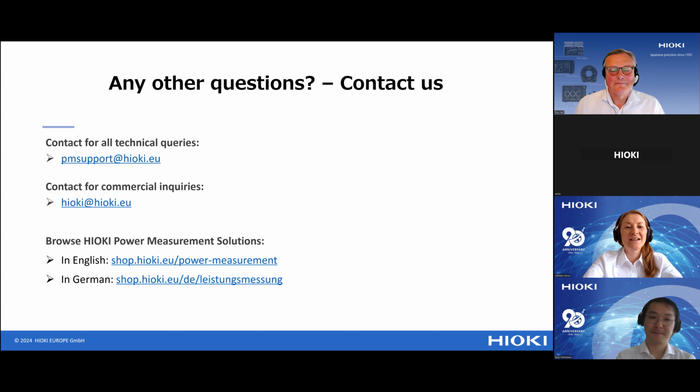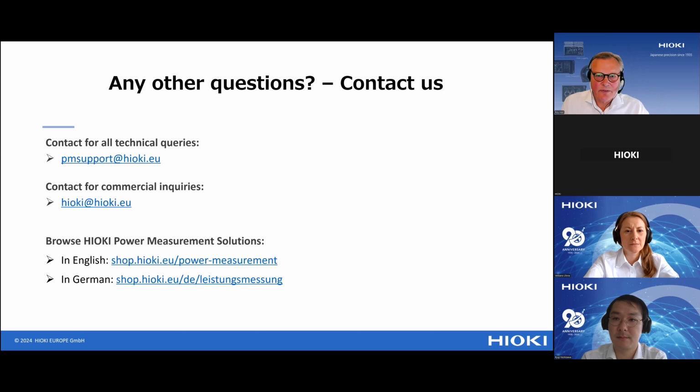Okay, perfect. Thank you. The same person has another question: how does update interval influence measurement accuracy and repeatability? Well, in our situation, we don't have any deterioration of the power accuracy when we reduce the data update rate. Even at 1 millisecond, we can guarantee the accuracy specifications of the power measurement with the PW8001.